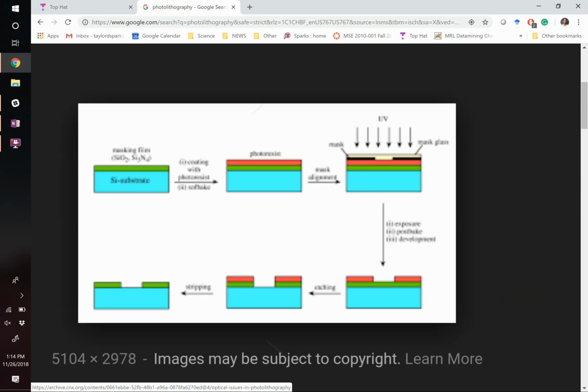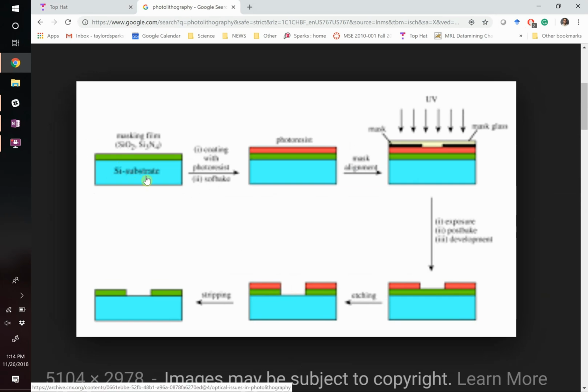That's terrible. Right? They start out with the silicon substrate up here, and it might have an oxide on the surface that you don't like. It might have silicon oxide there. So the first thing they do is they'll put a photoresist on top of that. A photoresist means that when you shine light on it, with the presence of a mask, the light will only see certain parts of your photoresist, right? And there's both positive and negative types of photoresist. If it's a positive one or negative, it tells you whether or not this resist is going to set up and become hard or stay a liquid. Because initially it's sort of in like a liquid gel state, where if you rinsed it, it would rinse right off.